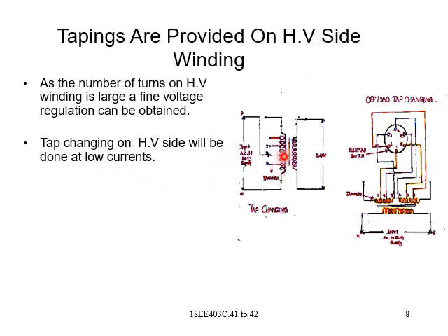During tappings from one stud to another, or one tap to another, when you move the terminal under load, some sparks may occur on changeover of the tappings. That spark is due to huge currents. If the currents are less, the sparking is less, and if the currents are more, the sparking is more.